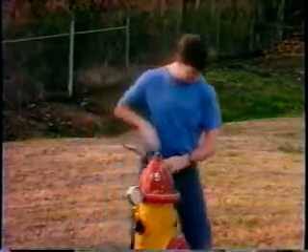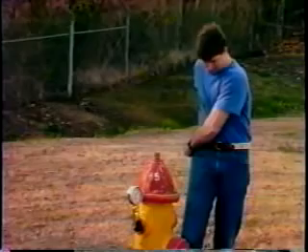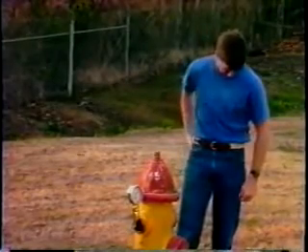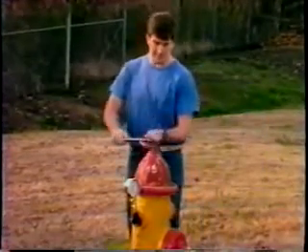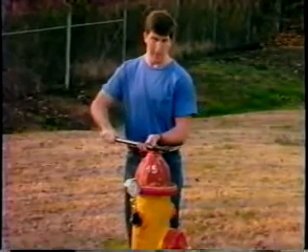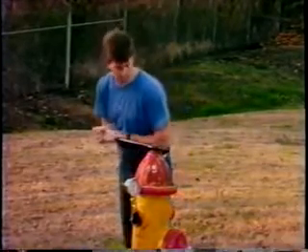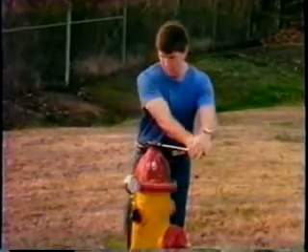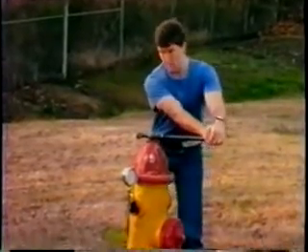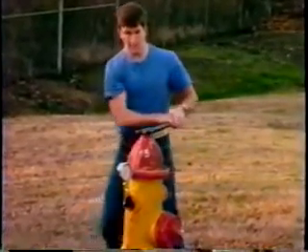Once the pitot gauge is in place, the individual at the float hydrant contacts the individual at the residual hydrant and indicates that he's ready to start the test. The individual at the residual hydrant then decides when it's time to begin the test. He then contacts the person at the float hydrant and indicates that it is time to start.